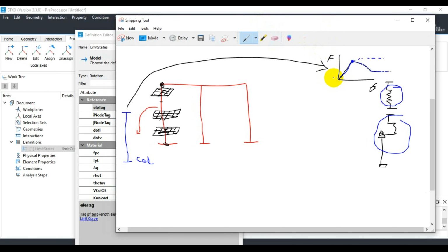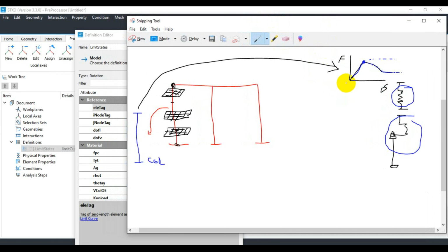So based on those limit states, there are two important failure modes in limit surfaces, based on the axial load and shear loads here. The first one and the second one, I will demonstrate those two here. So let's say we have that first curve, and this is the shear demand curve, and we have, in terms of displacement or drift, as is horizontal here.